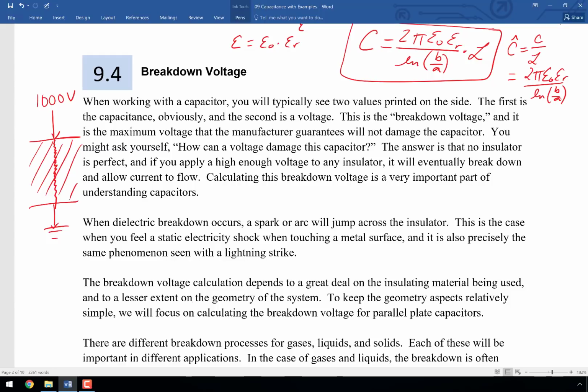And so if you have a little chip down here, just sitting there, not hurting anybody, and then here comes this person's big finger, and that finger has a whole bunch of positive charges on it. Well, as you touch, or even as you get close to it, zap, electricity is going to go from your finger into that chip, and there's a good chance it's going to find its way into one of those oxides and probably damage them permanently, as we saw over here on the left.